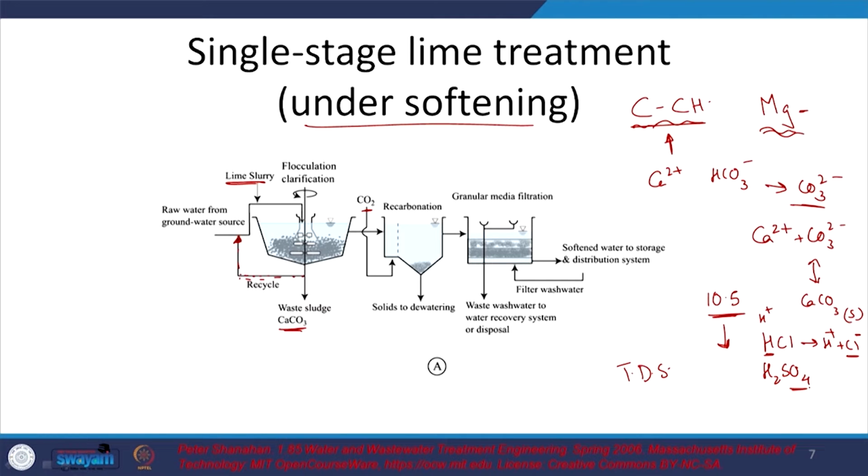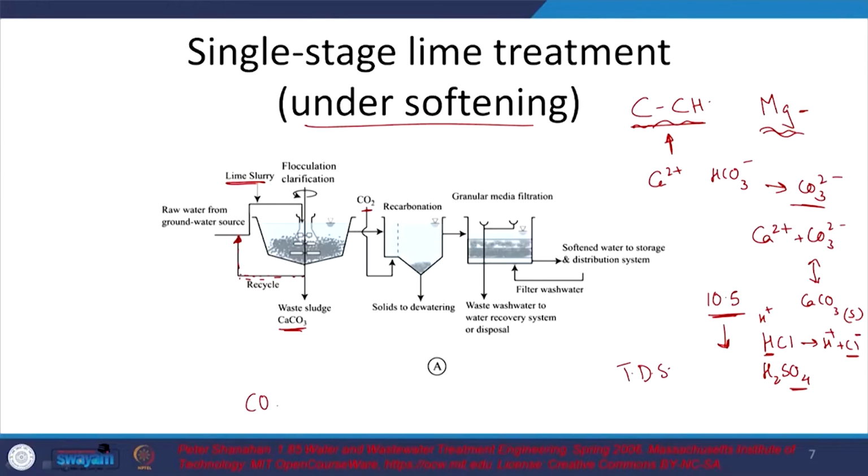So, I want to add something that will provide the required H+, and where the relevant anion is something that I would prefer to be present in the water. So, what is that? It is nothing but adding H2CO3, and how are we going to achieve that? By adding carbon dioxide gas, it equilibrates with the carbon dioxide in the aqueous phase, which equilibrates with H2CO3. H2CO3 is an acid, and depending on how much you add, it will stay as HCO3-, or not so much as CO3 2-, but this is the equilibrium. So, you can release H+ depending upon the pH and pK of the system.